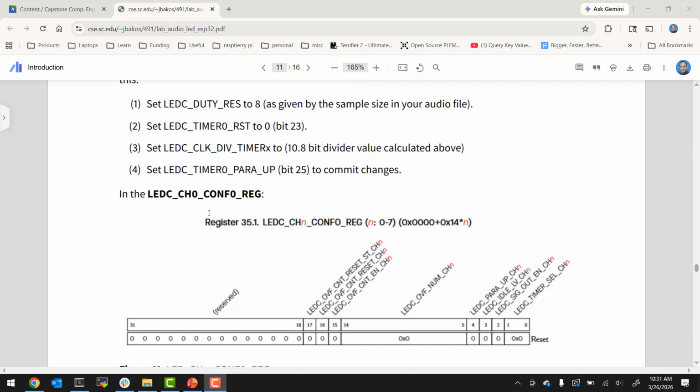Okay. Oh, by the way, I don't know if I ever mentioned this in lecture, but when you run the Arduino, you're actually getting version 1 that doesn't have debugging capabilities. But if you run Arduino-IDE, just a different command, if you add -IDE, you get version 2, and the debugger should work on there. You guys with me? When I say debugger, I mean setting breakpoints and inspecting variables and that kind of stuff.